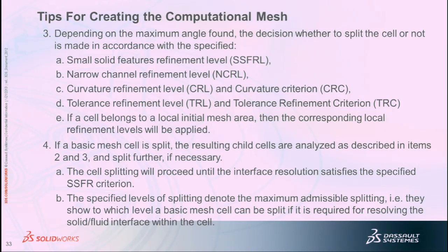So it worries about small solid features, narrow channel refinement, curvature refinement. It does look at the curvature and tries to further refine the cells around particular curvature. There's actually criteria that you can go in there and change. But again, the default settings are usually very good.